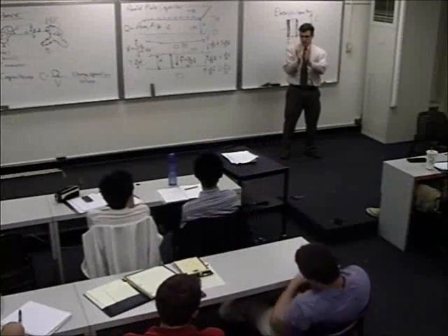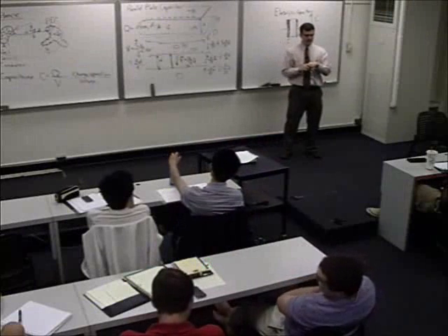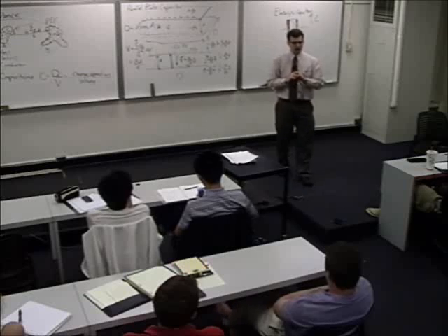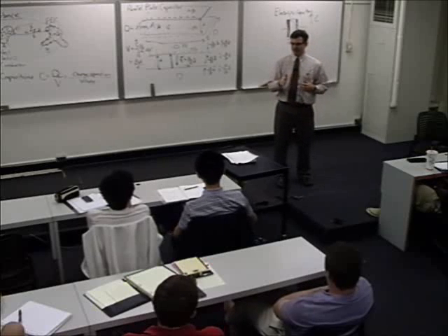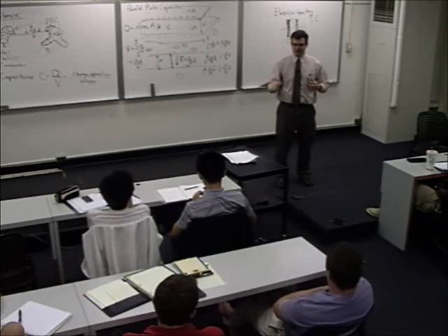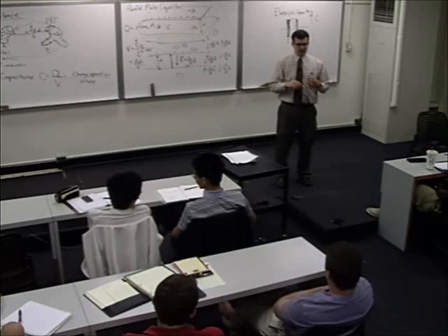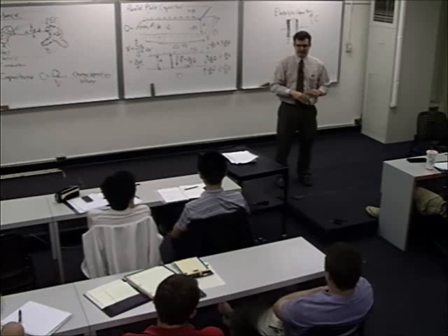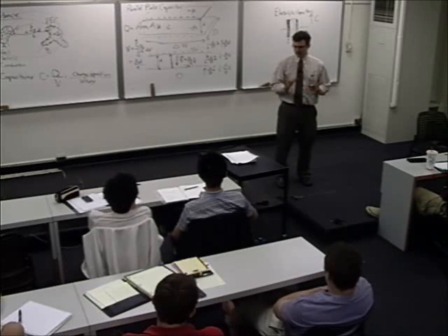And I had to do the equivalent of 3041 there. One of our labs involved a little power experiment where you had to rectify power and then use an electrolytic cap to smooth out the ripple. I don't know if you've ever done anything like that in one of your electronics experiments. I gave this lecture very clearly: there's a plus sign and a minus sign on the electrolytic cap. Put the positive voltage on the plus side and the negative on the minus side. Don't switch it, or else it's going to explode.